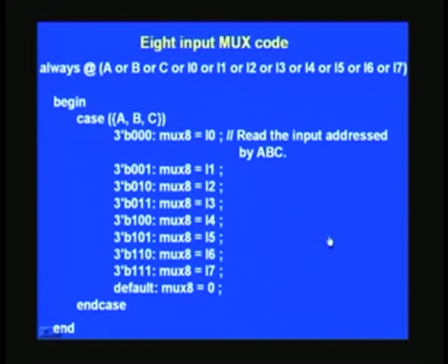So what you have seen earlier is a mux circuit, and this you are already familiar with. It is an always block with a begin here and end here, and now we have added one more statement called case, which is very close to C's case, except that this is actually hardware design, so bear that in mind. We have also seen a concatenation of 3 numbers here, and that is how we put them within brackets. This also is a mandatory thing.